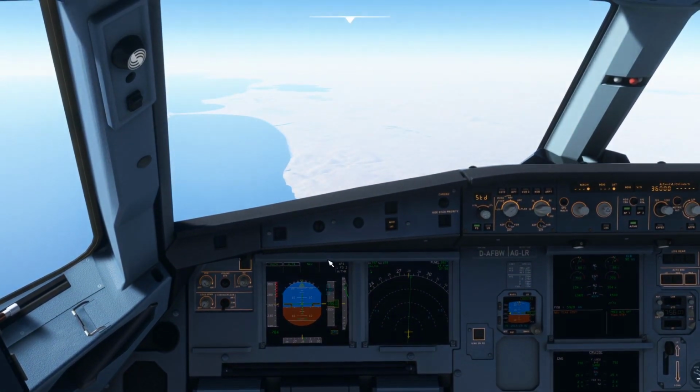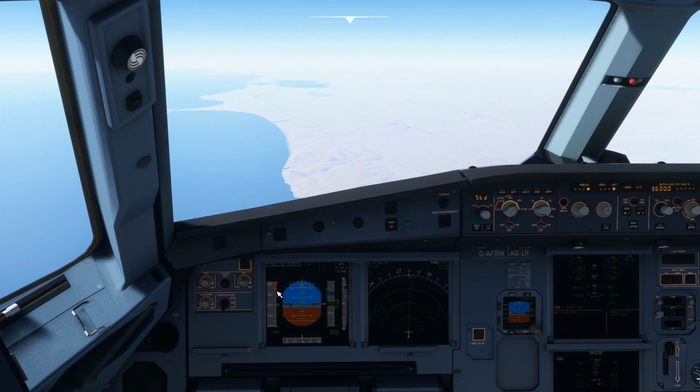If you remember, before 30,000 feet, the plane was flying at 290 knots, if I remember correctly. Yes, if I'm not wrong, the plane was climbing at 290 knots as per the autopilot. So as we were climbing at 290 knots, but after 30,000 feet, the speed is set to 0.7 Mach. So now 290 knots is not the speed of the plane, rather it's 260.